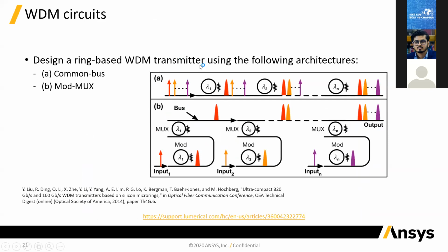So here is a block diagram, a cartoon showing the concept of wavelength division multiplexing. What wavelength division multiplexing allows you to do is, using a single channel, say a single optical fiber, transport a lot of data. The way you do it is that if you have multiple data streams that you want to transfer through that single channel, you simply modulate them at different optical wavelengths. So if you have, say, 3 sets of data, you modulate them at different wavelengths. That's where the wavelength division multiplexing comes in.